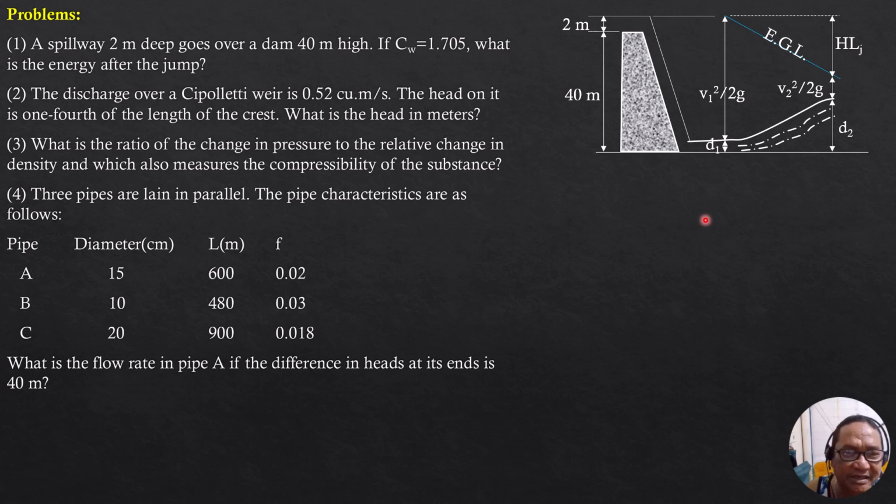So the discharge capital Q for a rectangular channel is this coefficient here. This is already greater than 1. So just like Francis formula, 1.84 length of the crest times head to the 3/2. In this case, 1.705 length of the crest, head to the 3/2. The length of the crest may be taken as 1 meter because there's no mentioned length of the dam. So we consider 1 meter width so that the discharge will also be small q.